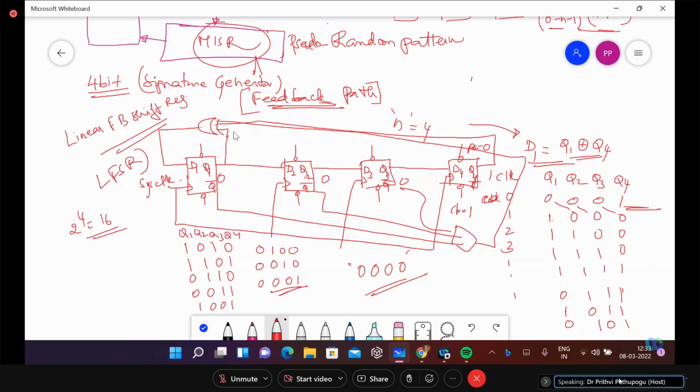This is already 1. 0 1, already it will be 1. 0 1, it will be 1. Over this becomes 1. All these are ones. This 1 will make another input of XOR to be 1, which means 1 XOR 1 is 0. This 0 will be shifted in. Now, if this 0 is shifted in, 0, 0, 0, this 1 discards and this 0 comes through.